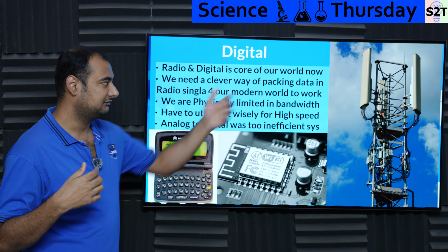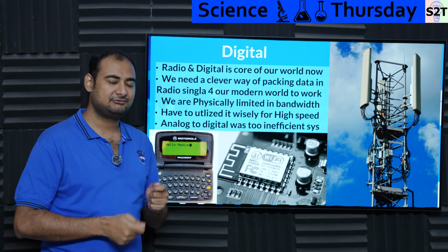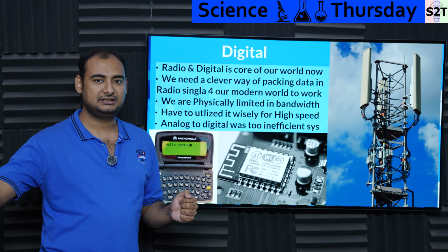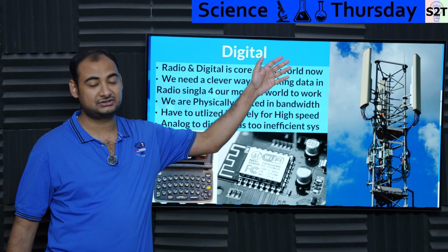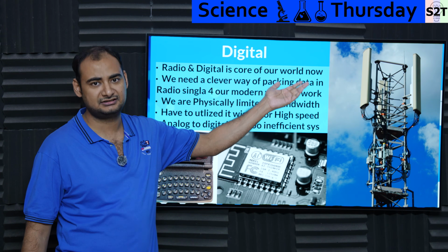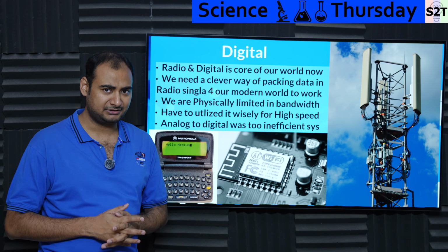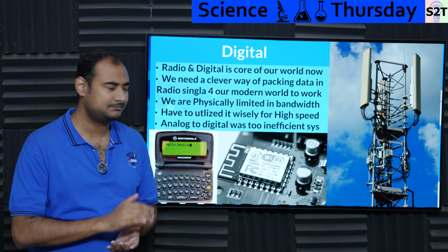So let's say this tower has to communicate with 10,000 mobile phones. If one mobile phone signal starts to create harmonics in other bands, it will interfere with those, and they will start to increase their signal output, and then more. Turns out they're supposed to be able to talk to, let's say, 10,000 people, but will barely be able to deal with 1,000. That's why harmonics also matter, and that's another aspect, like how much band buffer you have. All of those things play into it.